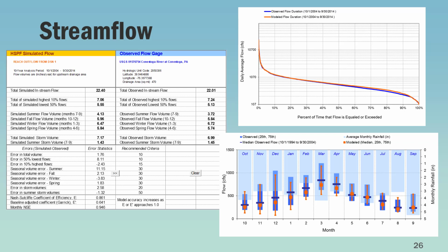One of the largest components of hydrology calibration and validation is streamflow. The approach adopted here is to look at all aspects of the flow pathway, which includes looking at the highest flow volumes, the low flows, the seasonal flows, flow duration, flow accumulation, and also the Nash-Sutcliffe model efficiency. For this study, since we are focusing on the transport of legacy sediment, it is important that the representation of streamflow at a daily time step is reasonable, because often a large amount of sediment load is transported during one or two of the largest storm events in a year.